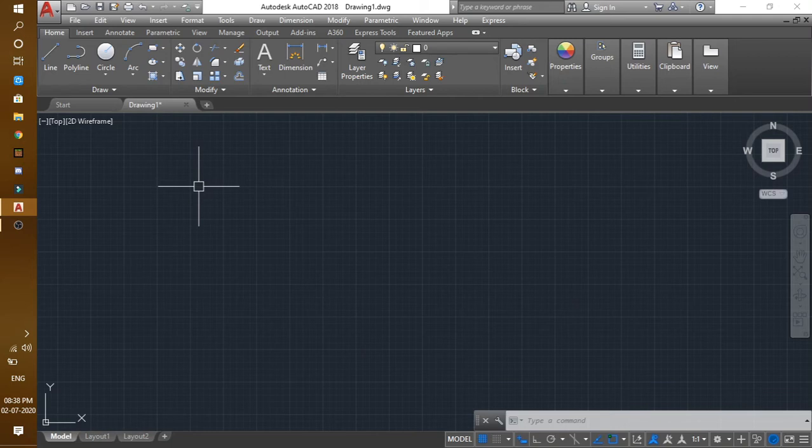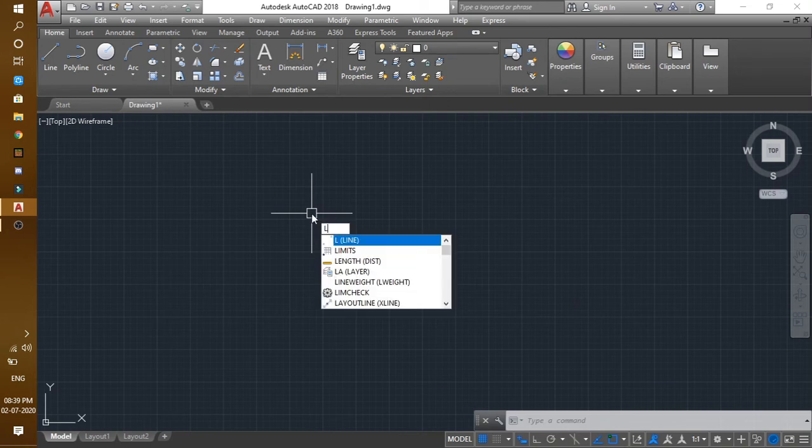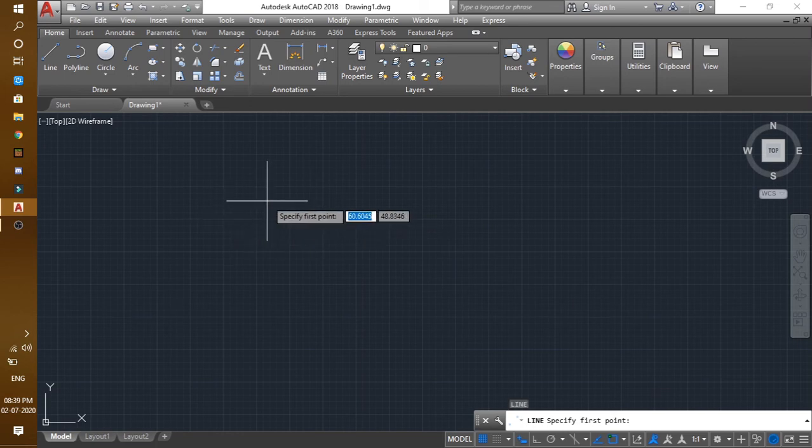Now moving on to the next method of forming a line. The next method is probably the most useful, which is forming lines with an inclination, that is with a certain angle, or your desired angle, and obviously length. So again, to start, just use the line command. This time let's use the line command shortcut, that is L. Just type L and press enter. Your line will be selected.